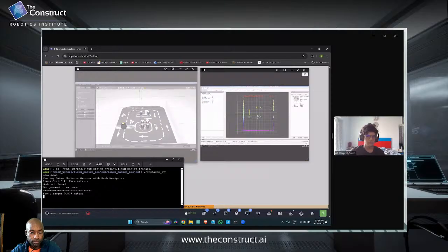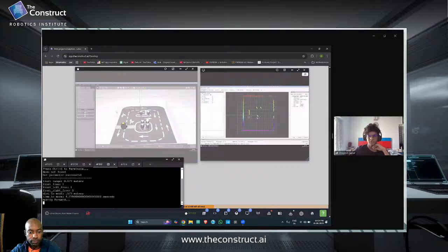So first it takes the sensor values. It takes multiple sensor values from the front left side, front right, and the right side. Using some basic if-else conditions, it determines its direction to move. As the front was free right now, we can see that all three directions were free, so it decided to move front for a certain